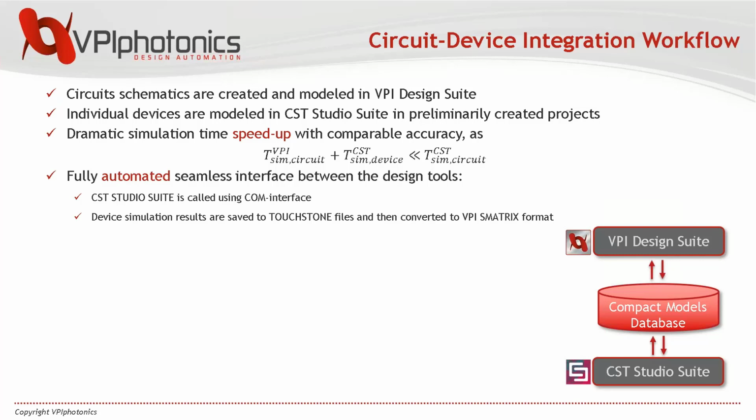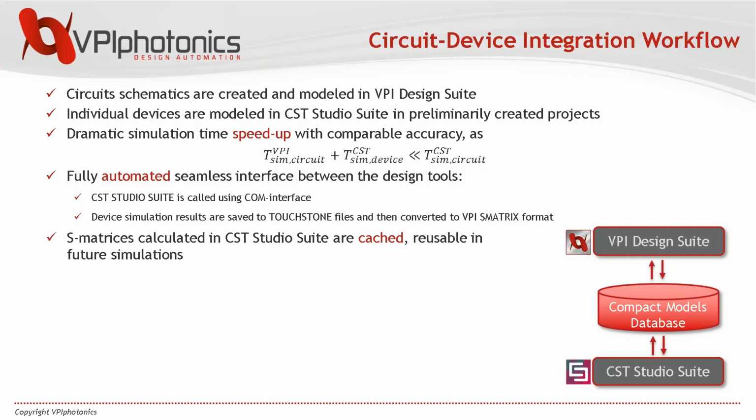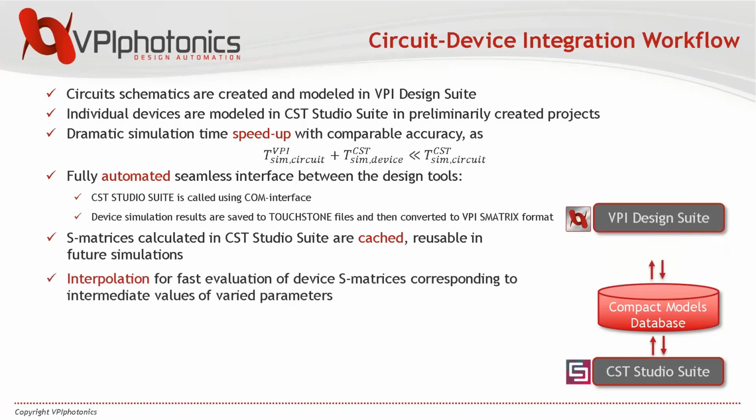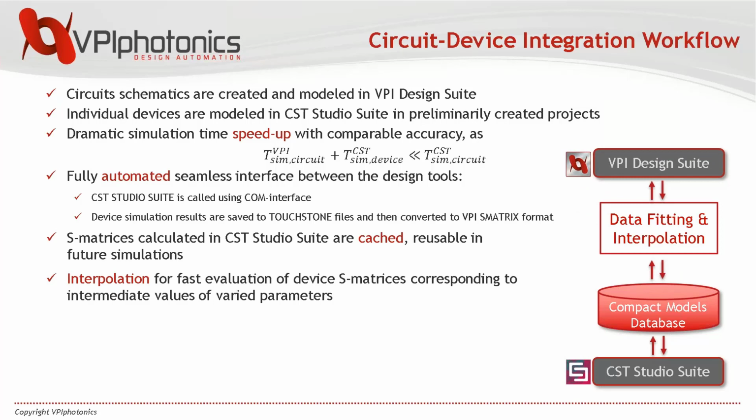So CST Studio Suite is called automatically, and Touchstone files are automatically converted to VPI's matrix file format. And so there is also no need to calculate these S matrices with CST Studio Suite every time. Instead, they could be cached and reused in subsequent simulations. Moreover, for the components which differ by comparatively small variation in parameters, interpolation techniques are applied.